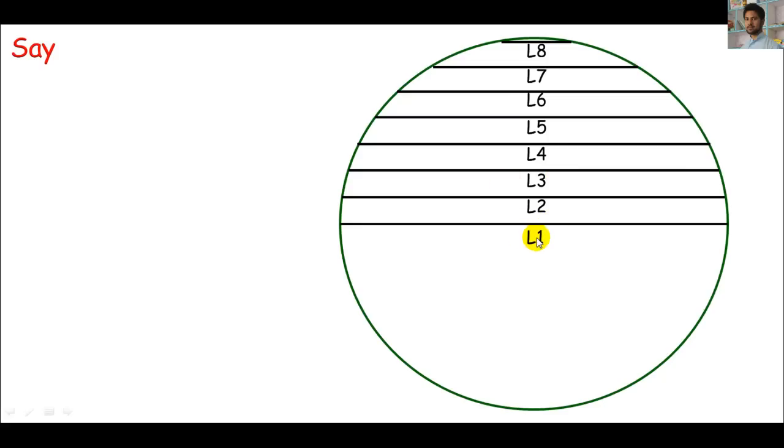You can clearly see L1, which means length of bar 1, is just the diameter of this slab. What about L2? Now this is a little challenging, but it's not, alright? You can find it using Pythagorean's theorem, which is L2 must be the square root of R square negative H1 square.